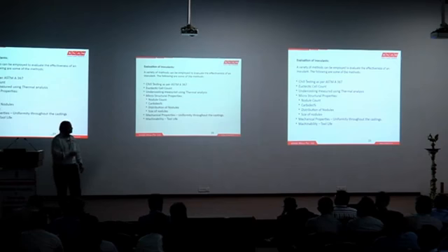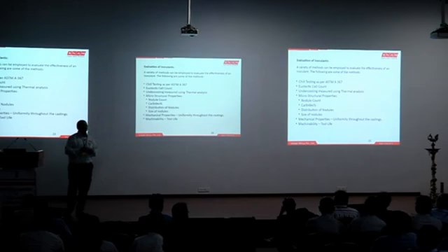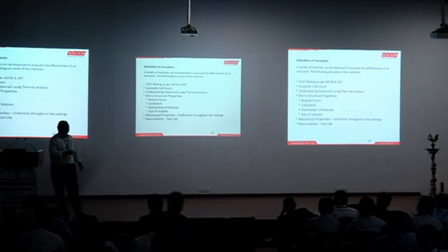Microstructural properties are the final responses a customer relates to his end properties, say for example, strength, yield strength, low temperature impact resistance. So all are related to the microstructural entities. Nodule count: everybody expects zero carbides, or if allowed, in the workable range.